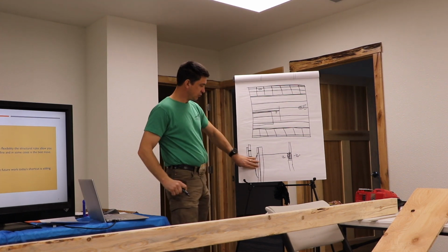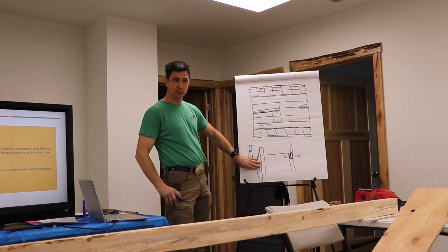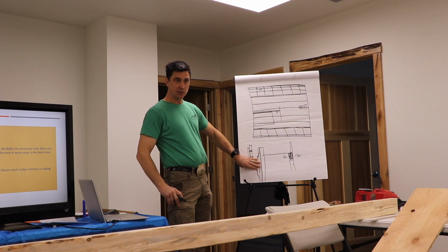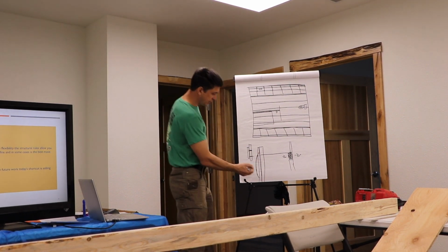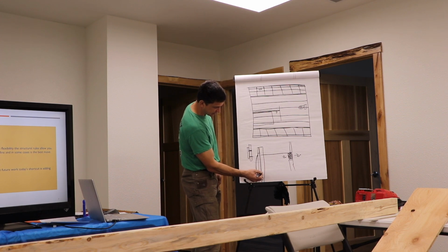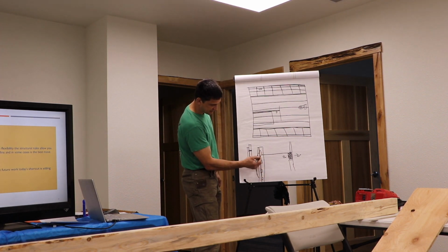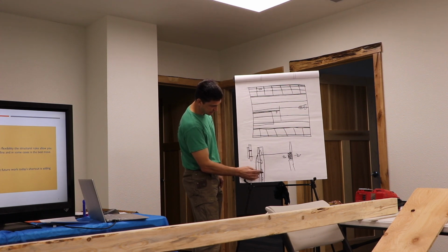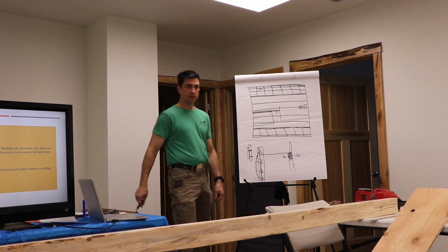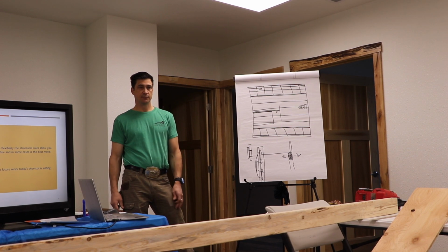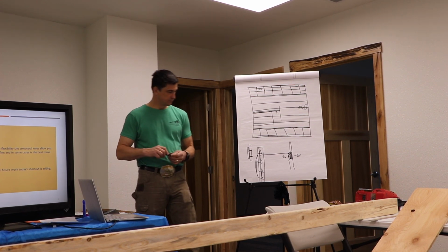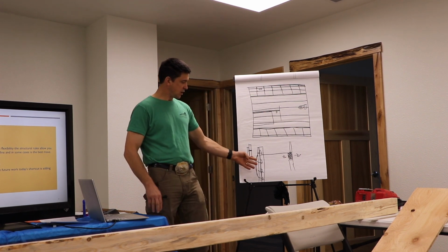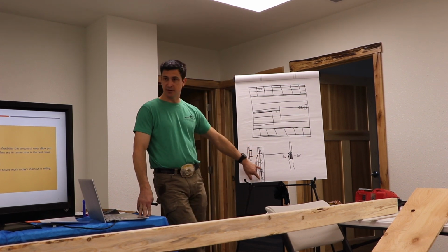When I put my drywall on this wall, or it's going to be crooked. My corner will be crooked. But when I put ladder blocking in here, if this stud is decently straight and then I nail this one to that, is my corner going to be straight? Yeah, it'll be beautiful. So that's why I want to see it done this way.